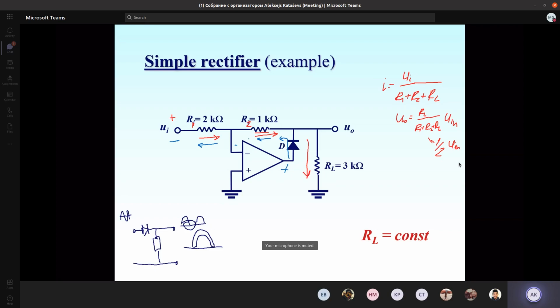So that means that our amplifier will be in a feedback. We have a feedback now. In the positive connection, the diode will be closed, and we could consider there is no connection at all, so the amplifier output has not been connected to U out. Now it's connected through the diode, and we may neglect the diode a little bit. We will neglect the diode, consider that there is no diode at all, and we have a connection. We have a feedback. So if we have a feedback, our amplifier immediately forms an inverting amplifier.